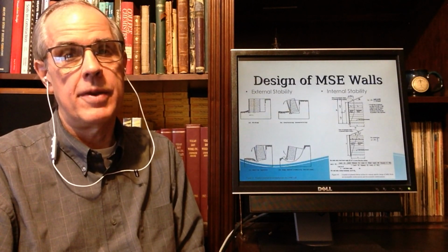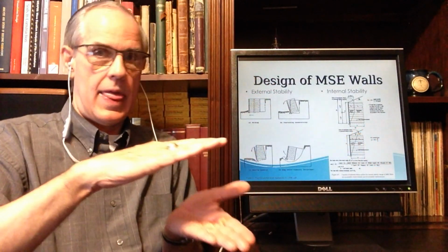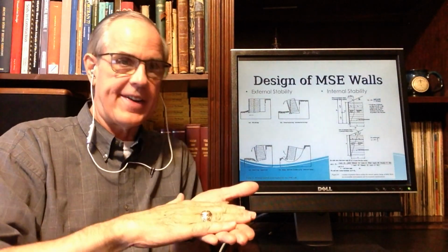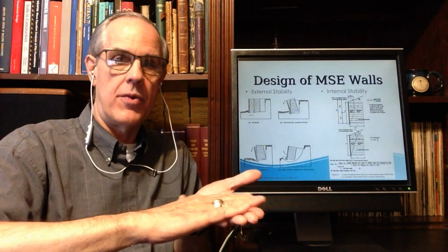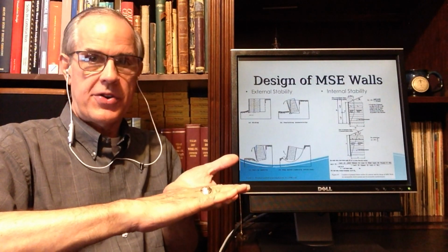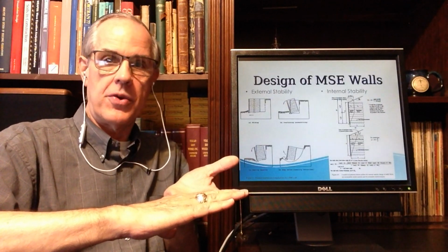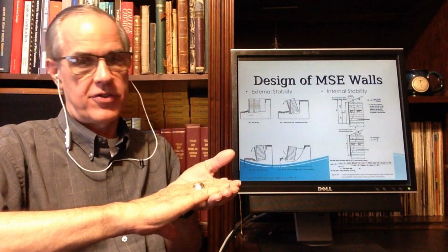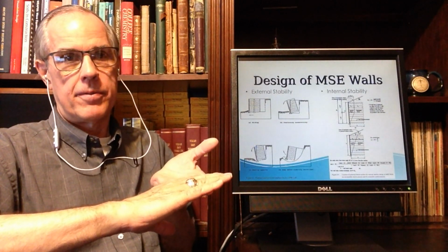So it should not be an issue. Basically that effective stress acts vertically on whatever reinforcement grid I have here. And when it does, that friction, it's another Coulomb block type of friction, will resist this reinforcement being pulled.